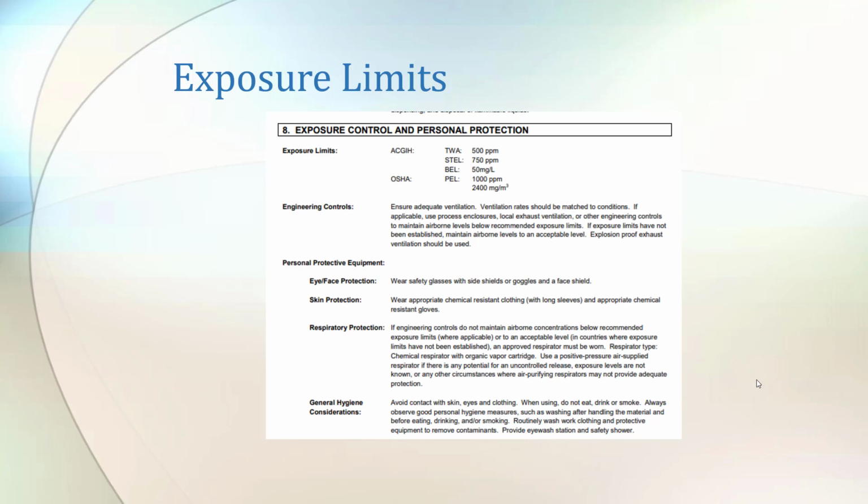So where it talks about 500 parts per million, that's in the air. So if you had an air monitor and you were monitoring real time, which they do make, and it became 501 parts per million, your air monitor would notify you that the atmosphere has become unsafe to breathe.